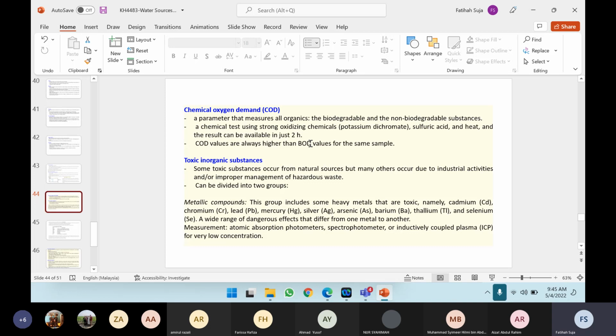So usually if you cannot sample throughout, let's say if you want to get the value for both the BOD and COD, you will have a few samples for both BOD and COD so that you get the ratio, and then you will only monitor BOD maybe once a week, and the rest you measure the COD, because COD will only take about 2 hours.